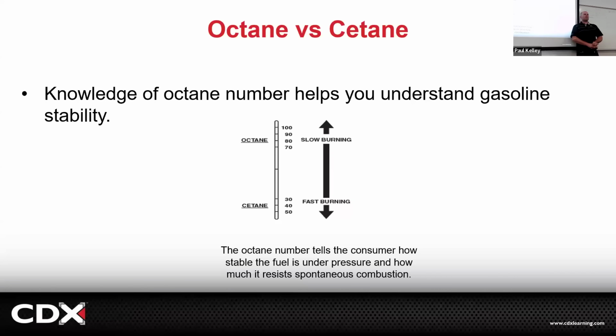87 octane is fine. It can be very high quality 87 octane, and that could be exactly what your car calls for. Most typical average economy cars do call for 87. There's a reason they call for 87. If you think you're helping it out by running 91 octane, I'm not really sure about that. It kind of depends on the application. Now, if you've got a car that's supercharged, turbocharged, really high performance, and it calls for 91 octane, yeah, you really need to run the 91 octane.